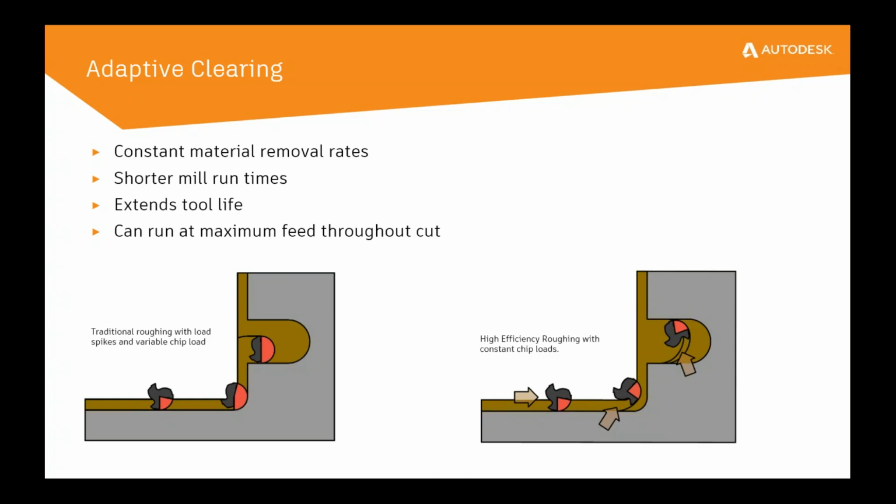You'll see the same thing as it enters that pocket. It doesn't just dive into that slot to machine it out. It starts taking it in swipe cuts. So there's an example. It's got 2 cuts drawn in there. It's going to do a swipe, come back, take another swipe. So it's basically doing a larger circle progressing forward.